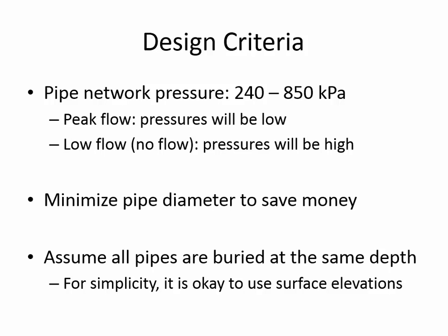Jared? It's just a junction. Yeah, and at each of those junctions, the way you specify a demand is in the junction table, in the demand collection column. That's where you type in an outflow. And if you don't remember exactly how to click to do that, it'll be in the little summary video that I link to in my upcoming email.